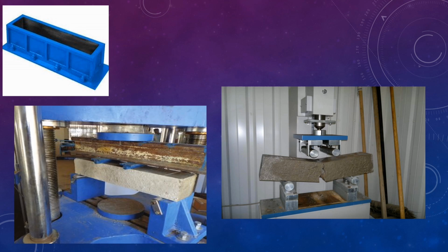And this is the 2-point loading system. These are the two supports of the machine where we are loading the concrete beam, and we are marking 2 lines at the edges, 5 centimeter from this end. We are marking 2 lines, 5 centimeter from this edge and 5 centimeter from this edge. That is this loading line, and we apply the load from the top through the machine.